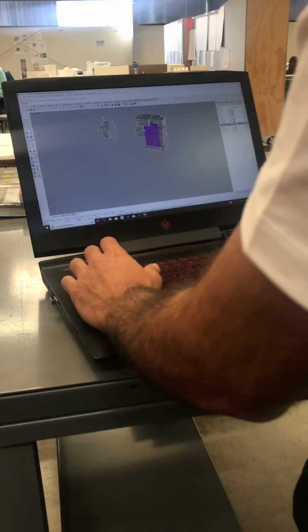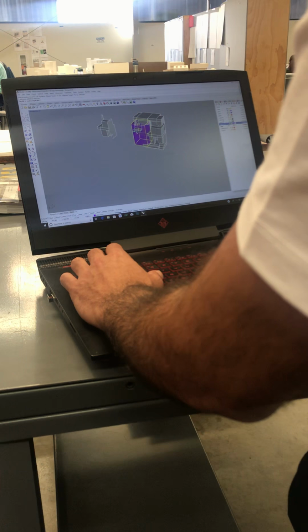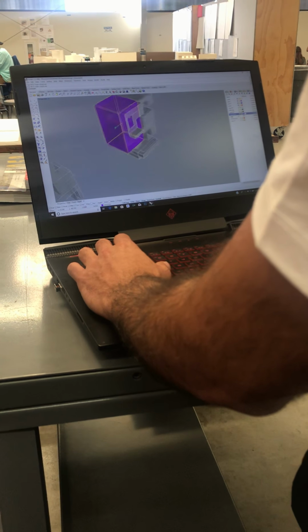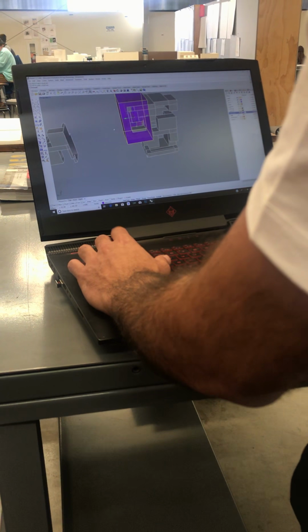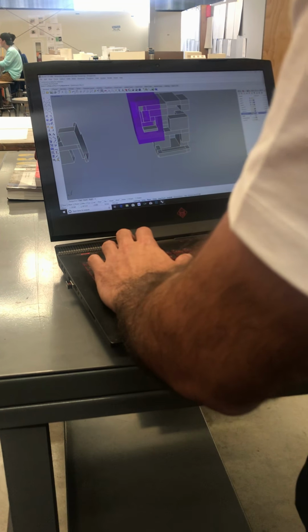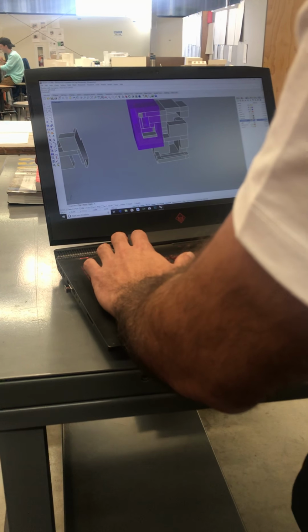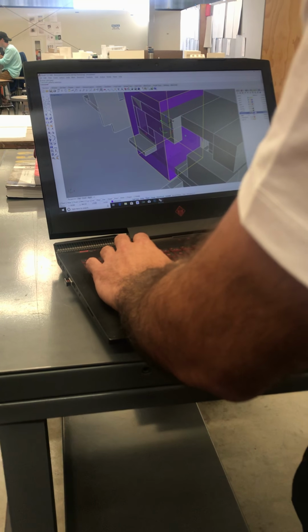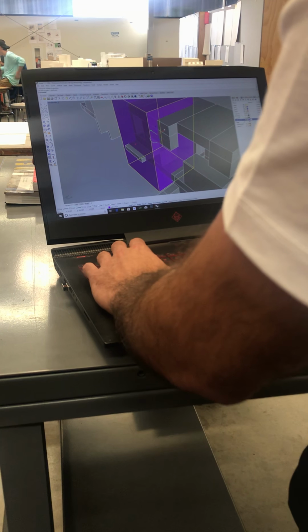Then let's do 2 more quickly, 2 more crops. I want to crop, let's say, this area. That looks pretty good. So I'm going to do another Boolean split, and I'm going to select this as my cutting box, and it failed again, probably because these are overlapping. So I'm just going to move it a 1/2 inch over this way.